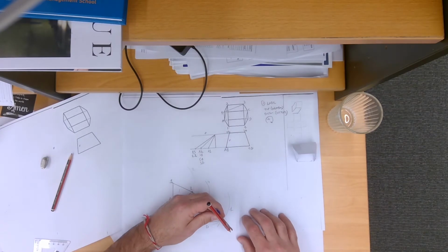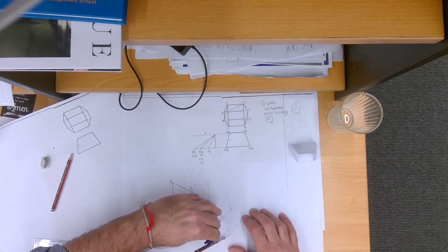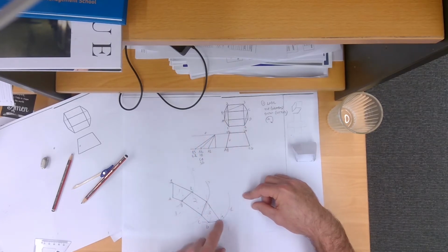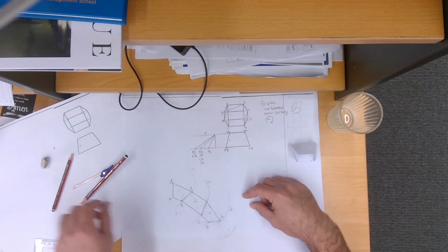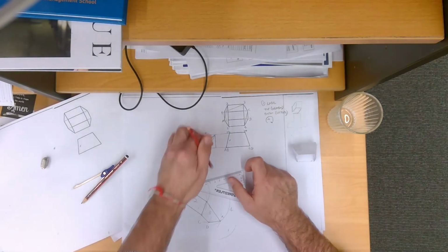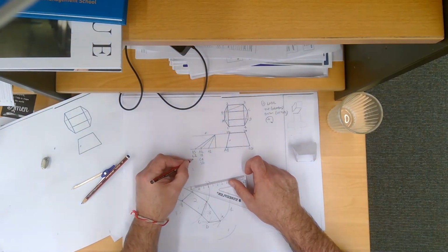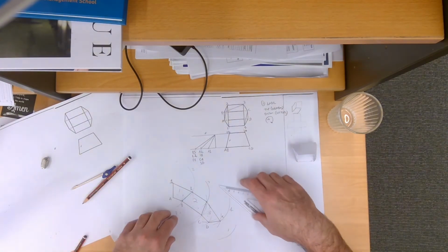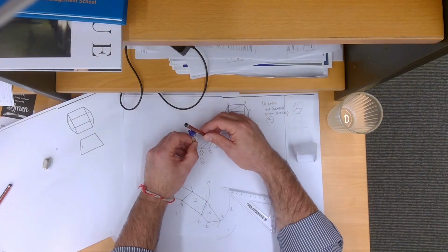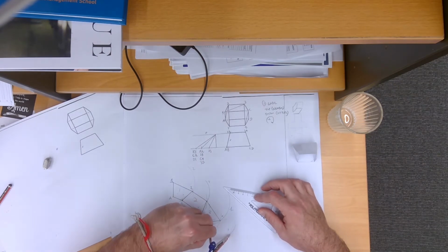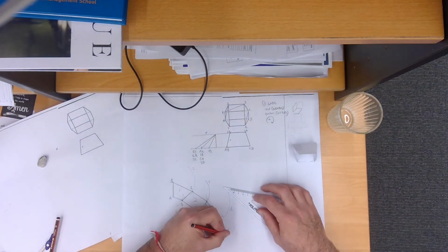And we're going to swing our arc. And we need to find something else that'll run to the 1. So we've got 1, 4. We need to work out our D1. Okay, so we haven't got a D1 in the face, but we know that D1 is going to be the same as B3 because these two faces are symmetrical. So B3 is also going to be like D1, so we can use this one here. So we grab this length here, our D1, we swing from D across, and we end up where they intersect here.